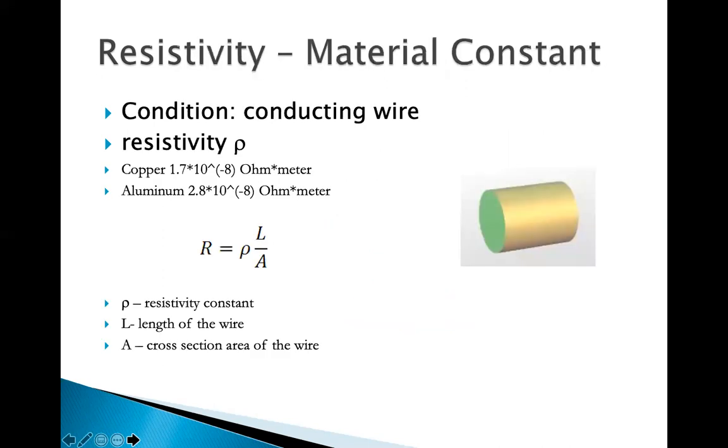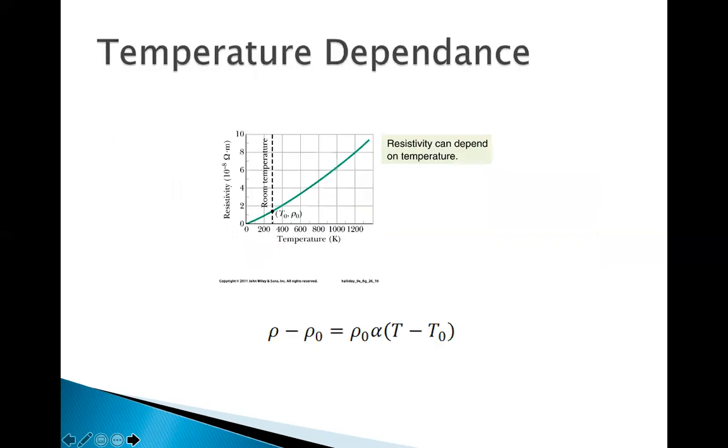Well, let's look at electric wires because we use them very often in all kinds of circuits. If we consider a wire as cylindrical in shape, let's take a very short piece. The length is L and the cross-section area is A. The resistance equals the resistivity rho multiplied by the length and divided by area A. So the resistance is determined by the shape of the wire. The longer the wire, the more resistance. So whenever possible, we can use shorter pieces of wire to reduce resistance.